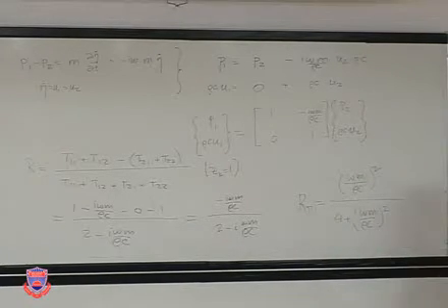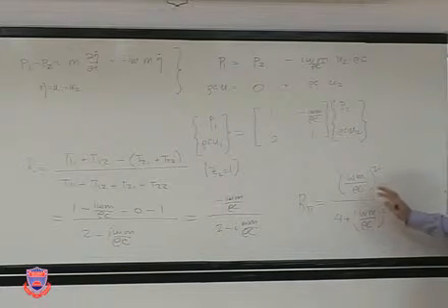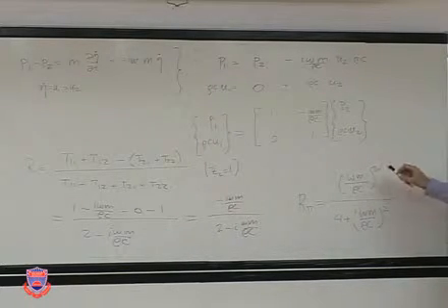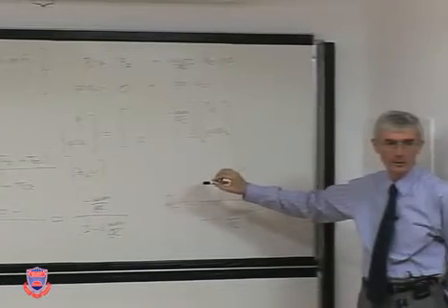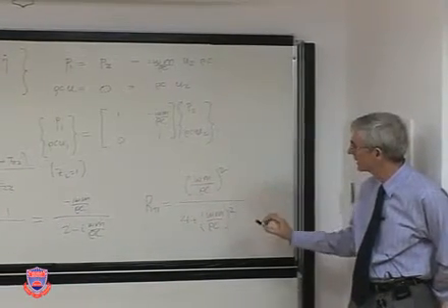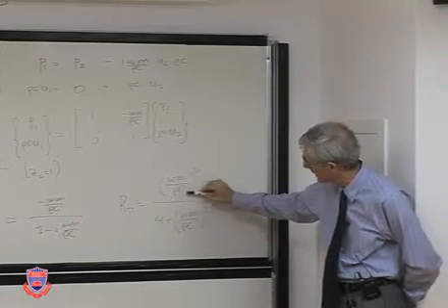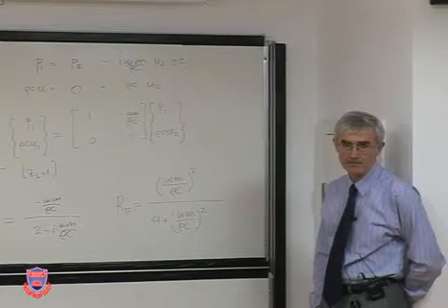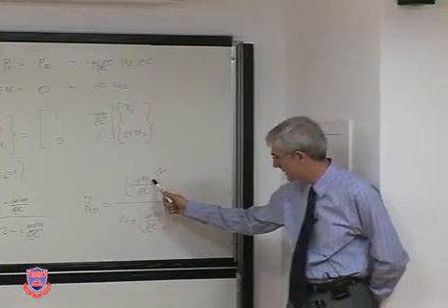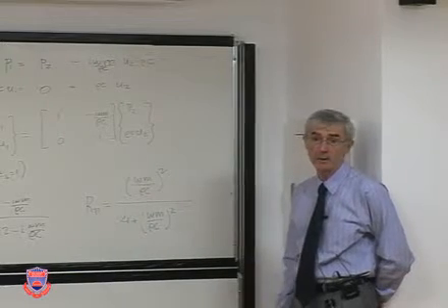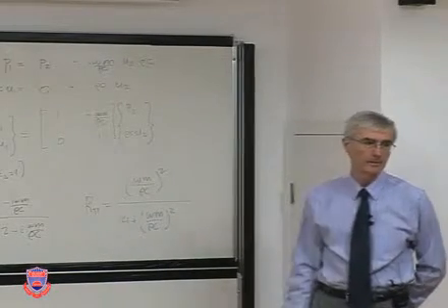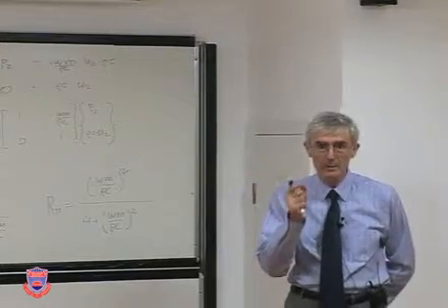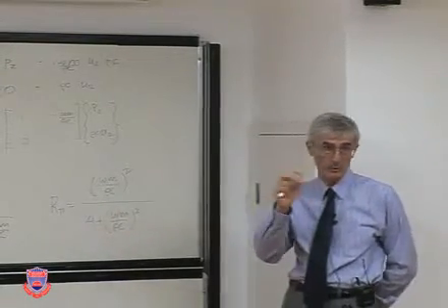What does all this tell you? We always talk about equations, expressions, telling you a story. When you look at this, of course, what is important is the top part, the numerator. What is the numerator telling us? Take a quick look at it. It's omega times m divided by rho c. Rho c is what? The specific acoustic impedance of the fluid medium.